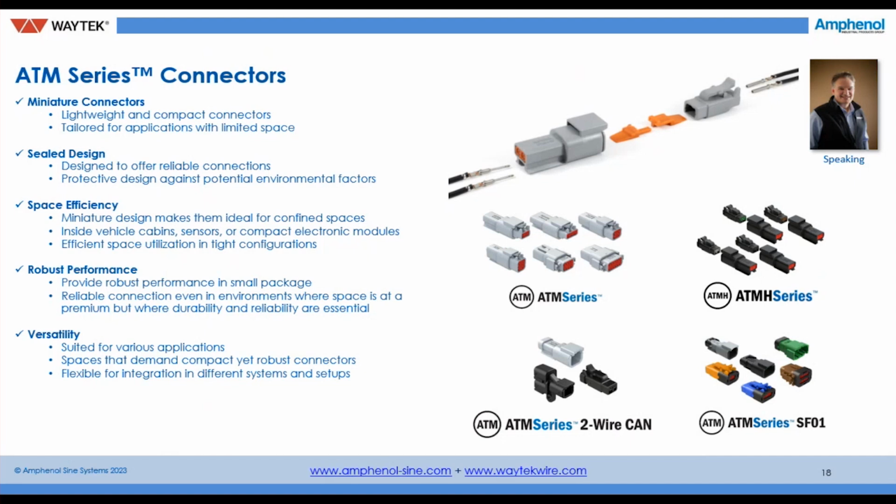ATM and SF01, the SF we call a snap fit. So that's that back cap that's on the back of our ATM. We kind of touched on that earlier. You know, the control of the rear seal. In certain applications, you're going to get introduction of some chemicals or maybe some lubricants, petroleum derivatives. You really want to make sure that you can contain that seal. This is a very low cost and effective way of doing that should you require it.